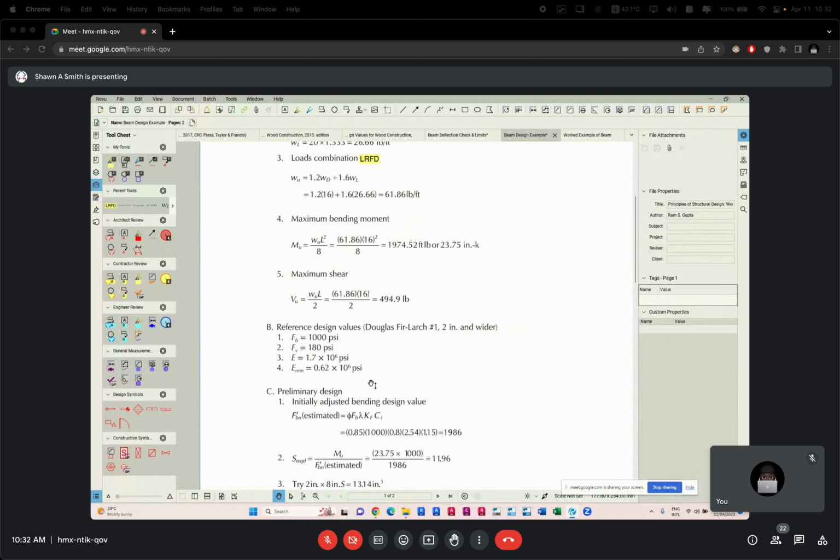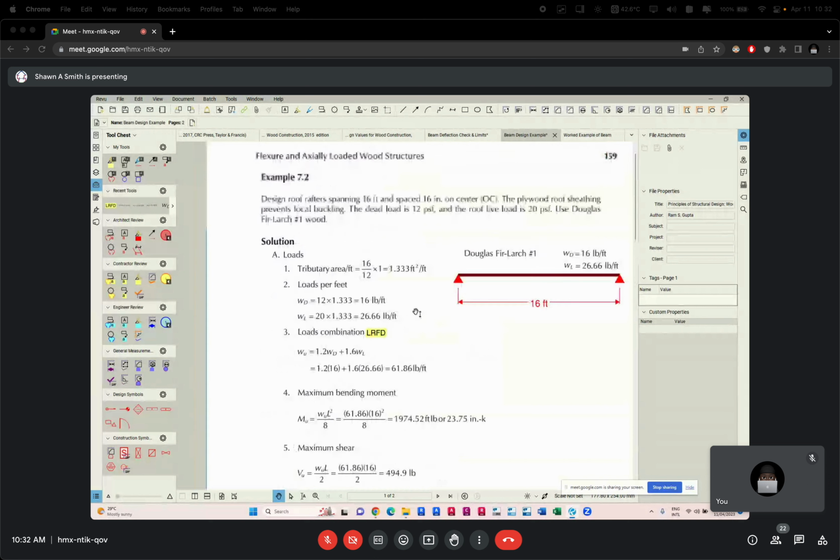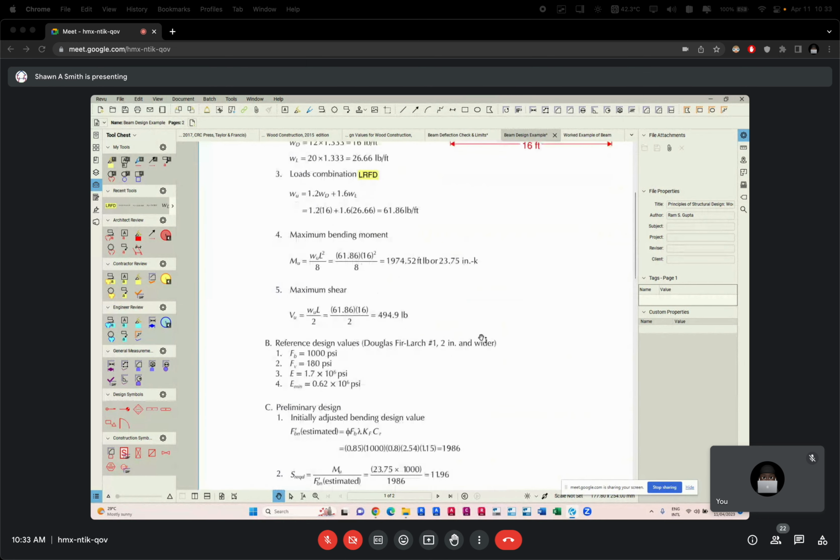All right. So these values, class, we know where to get them from. It's a matter of using the species and the size of timber. Again, the size was not given up here because the problem says design. It didn't say analyze, it said design. That means we are asked to find this, to make a size for it. So we have to start with something.